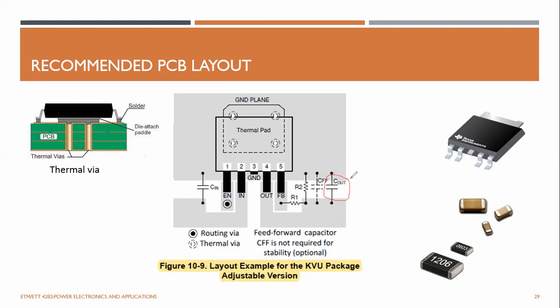For example, this ceramic multi-layer capacitor is like this. It also has a very small inductance, but it has this ESR and this capacitance. So when you keep your capacitor very close to there, you can get the desired response.